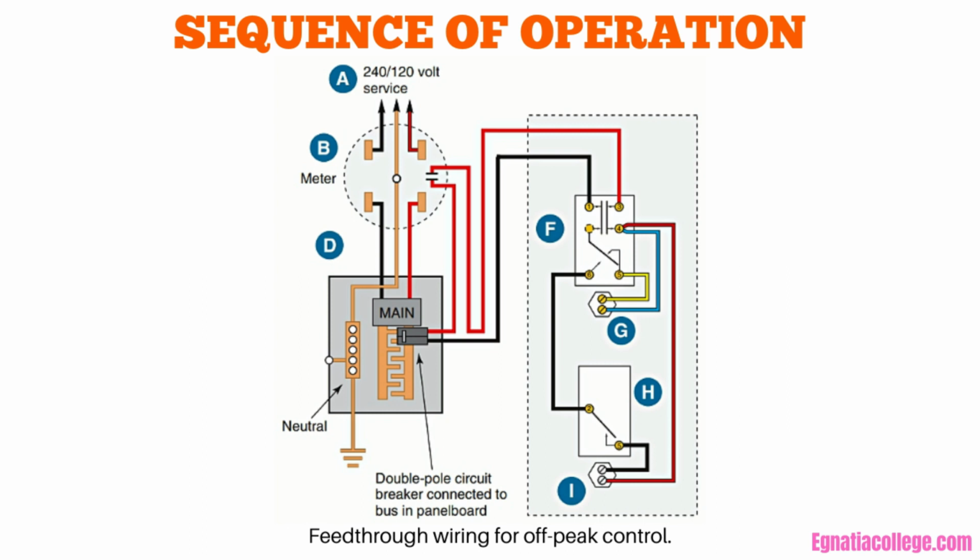When the water in the upper half of the tank reaches a temperature of about 49 degrees Celsius, the upper thermostat snaps over, the upper contacts are closed and the lower contacts of the upper thermostat are opened. The lower element now begins to heat the cold water in the bottom of the tank. When the entire tank is heated to 49 degrees Celsius, the lower thermostat shuts off. Electrical energy is not being used by either element at this point.